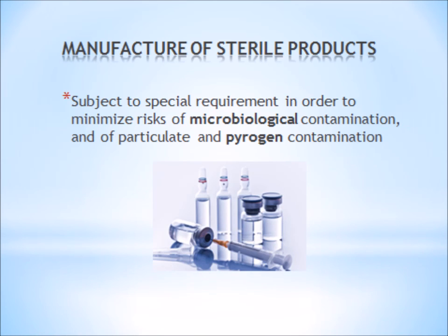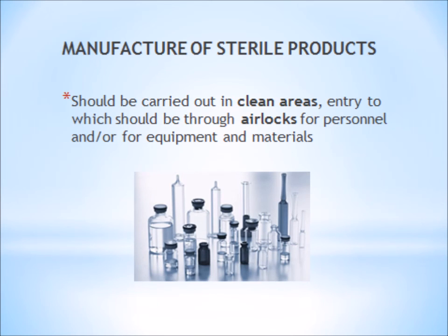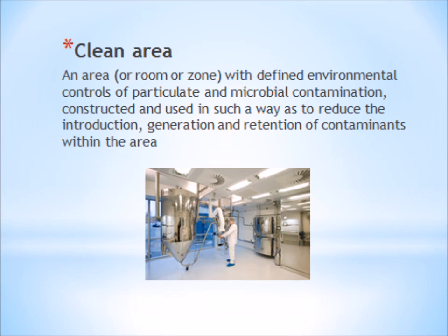Manufacture of sterile products. Subject to special requirements in order to minimize risk of microbiological contamination and of particulate and pyrogen contamination. Should be carried out in clean areas, entry to which should be through airlocks for personnel and or for equipment and materials. Clean area: an area with defined environmental control of particulates and microbial contamination, constructed and used in such a way as to reduce the introduction, generation, retention of contaminants within the area.